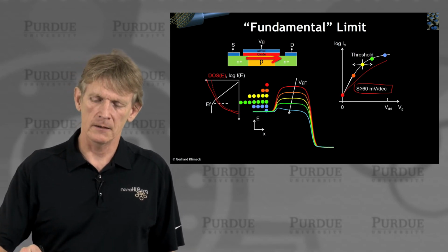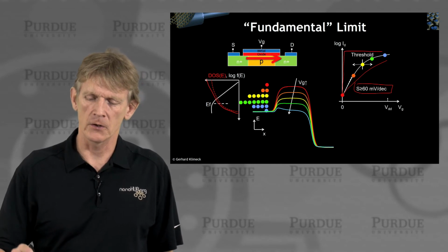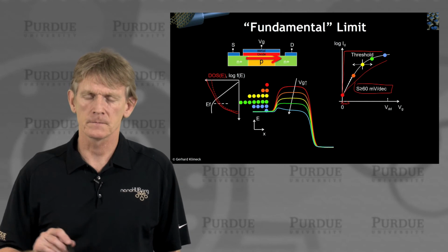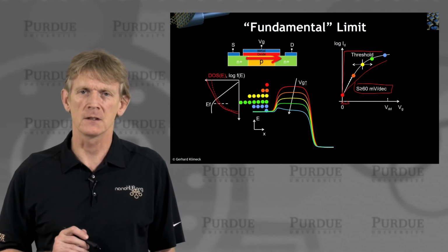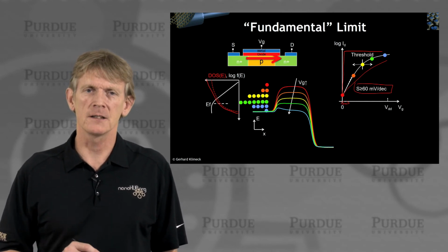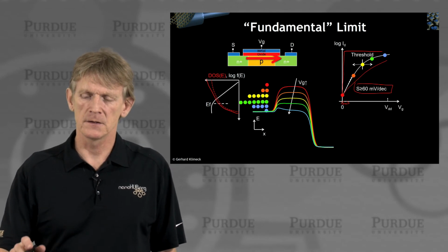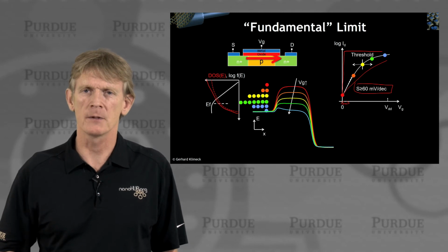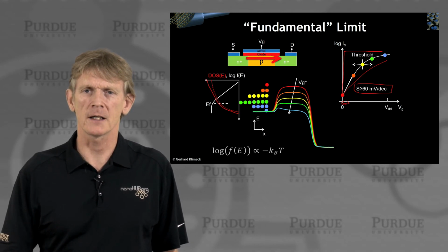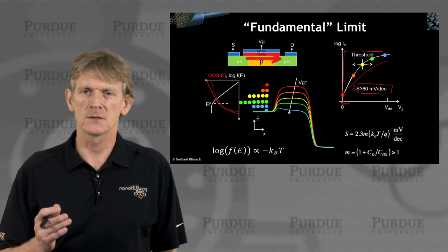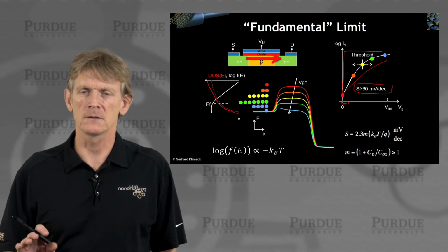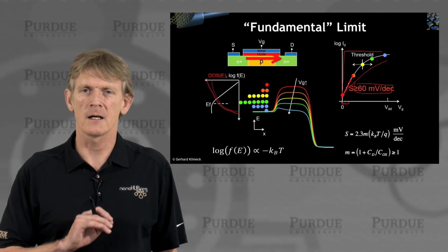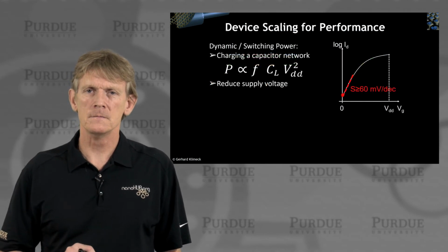Ideally, what you would like to have is a transistor that just turns on with very little voltage action, right? And is almost square, okay? That would be an ideal transistor. But what a CMOS device can give you is at best this transistor, okay? At best this overall shape with a slope of 60 millivolt per decade at room temperature. And this is the origin of the 60 millivolt. You know about the various capacitance in the system, etc. Okay?